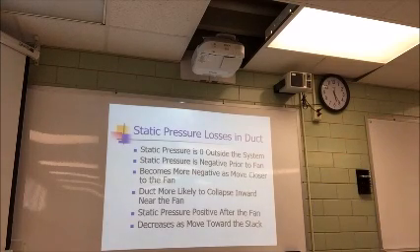Here's kind of some of the assumptions too with ventilation. Static pressure is 0 outside the system, and this is losses in the duct. Static pressure is negative prior to the fan. I've hit that one. As you move closer to the fan, what happens? The negative goes up. It moves quicker, it's faster.